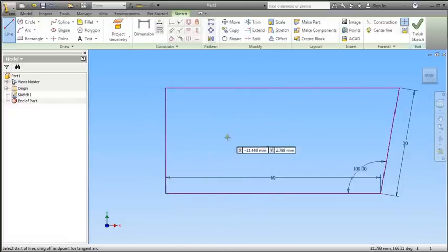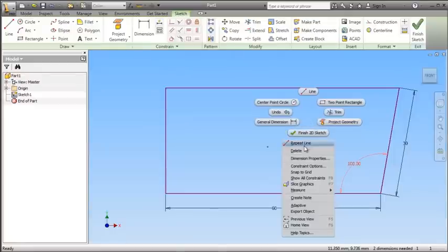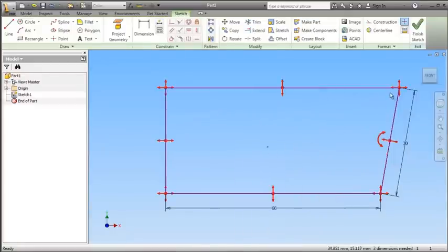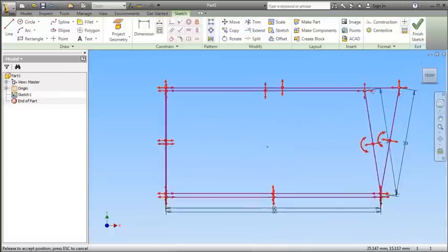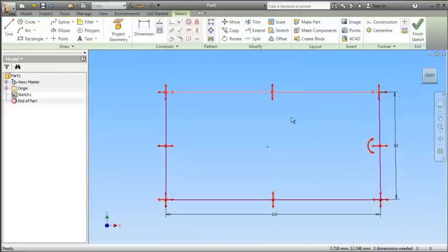Now that we've defined our sketch, we can now start to make modifications on it. For example, let's start to take a look at the constraint system. It will highlight perpendicularity, parallelism, the fact that that line is horizontal. All of the icons match up with the icons in the ribbon as well. If we make modifications, we can simply delete dimensions or place dimensions later on. We can see our degrees of freedom of the sketch so we can better understand how this sketch is going to behave. As we start to apply more constraints or more dimensions, these degrees of freedom will disappear.